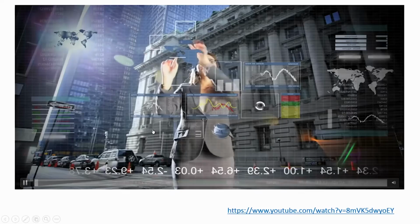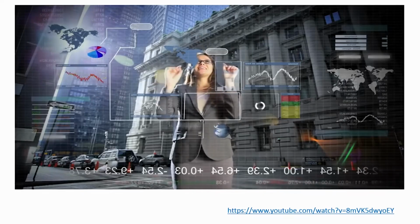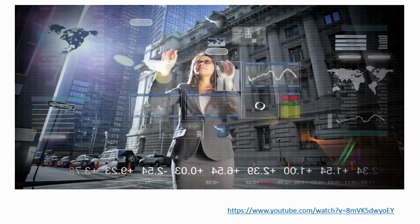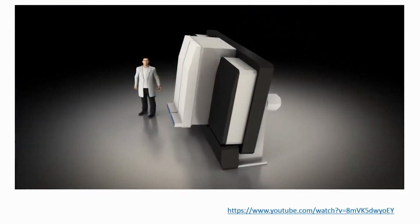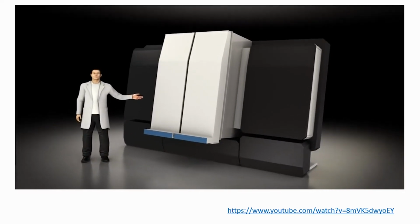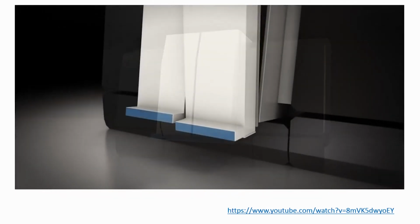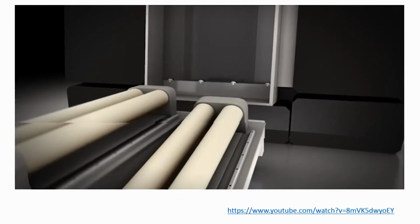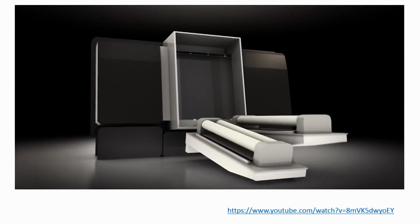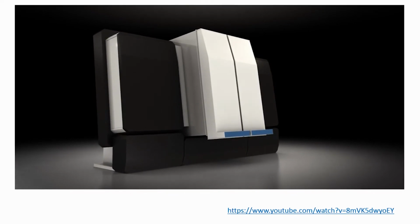The use of thin layers of materials is a crucial need in many industries. Architectural glass, displays, and touch panels or solar cells all contain thin films. The most important coating process to produce these layers is called sputter deposition. How does it work? Sputtering deposition is done in a vacuum chamber. The most common substrate for the thin layers is glass. The sputter system can have different sizes depending on the application. The source of the thin film material is a planar or rotary sputtering target of metal, ceramic, or even plastic. Molybdenum targets, for example, are used to produce conductive thin films in displays or thin film solar cells.